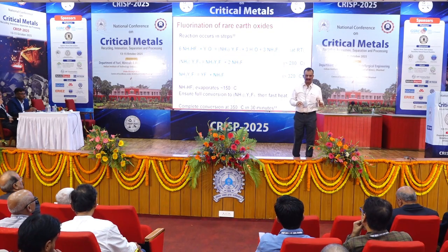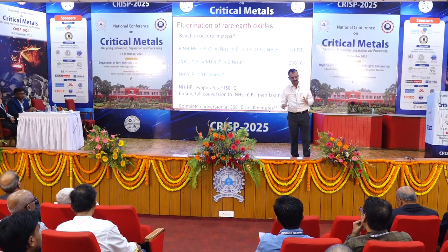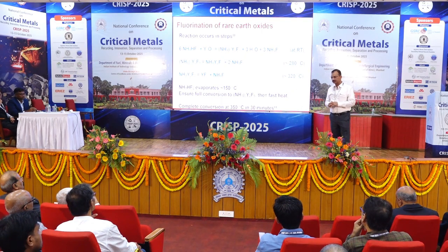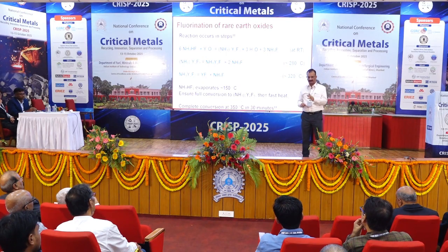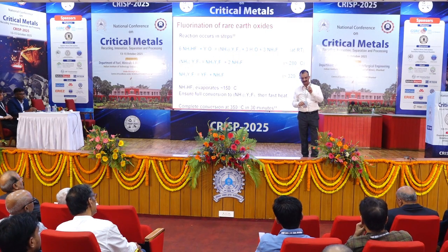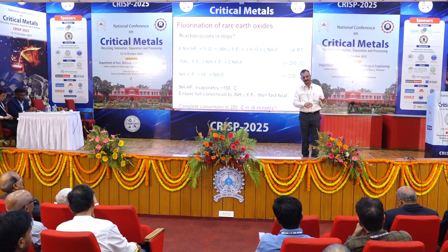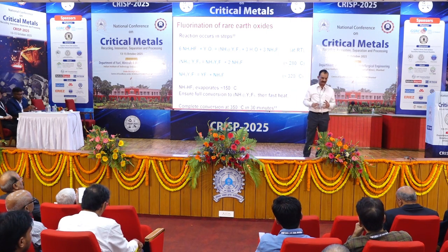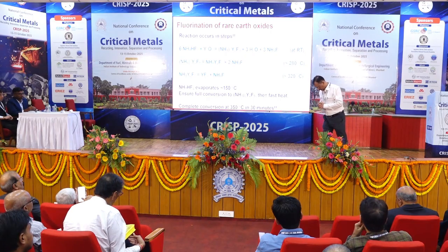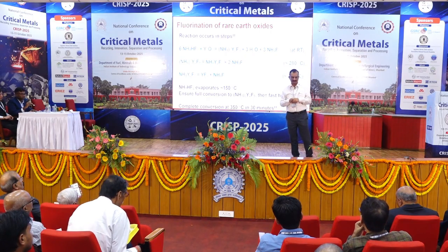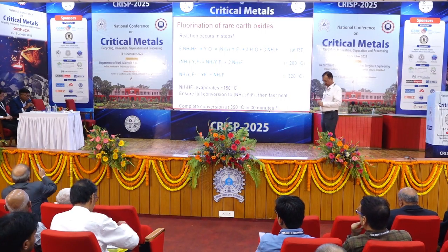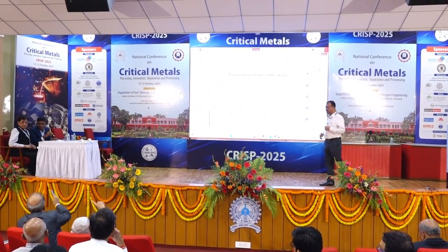Industry and academia have to come up with proper processing, and that can be told to industry, and they can do it. As far as tantalum is concerned, it's prepared by sodium reduction of K2TaF7. Directly it gives capacitor grade tantalum. But with Ta2O5 plus carbon, you take tantalum pentoxide and tantalum carbide, mix them together and heat under vacuum. That is practiced somewhere in Europe. That can be done. So, thank you, Dr. Alok Avasthi, sir.